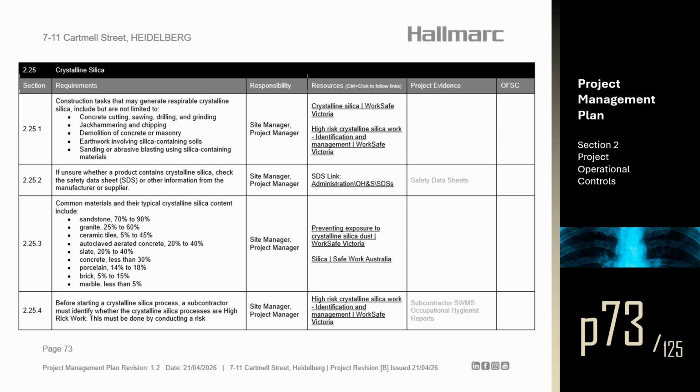If doing a risk assessment, the subcontractor must consider the following factors: the specific tasks or processes required to be undertaken with material that contains crystalline silica, the form of crystalline silica to be used, for example, brick, concrete or crushed rock, the proportion of crystalline silica contained in the material, the previous atmospheric monitoring results, the likely frequency and duration of exposure to crystalline silica dust, and any information about incidents, illnesses, or diseases associated with exposure to crystalline silica dust at the workplace.